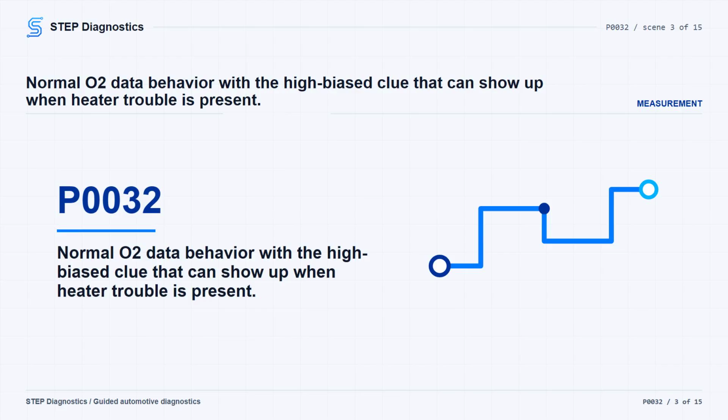Normal range of the O2 sensor output is a 0 to 1.0-volt analog signal, and a negative offset output of up to -1.0 volt may be introduced. Each O2 sensor return circuit has a 2.5-volt bias, so the bias signal voltage should switch between 2.5 and 3.5 volts on a normally functioning sensor. When the heater side has a problem, the bias signal voltage can read high and usually stays above 4.0 volts.